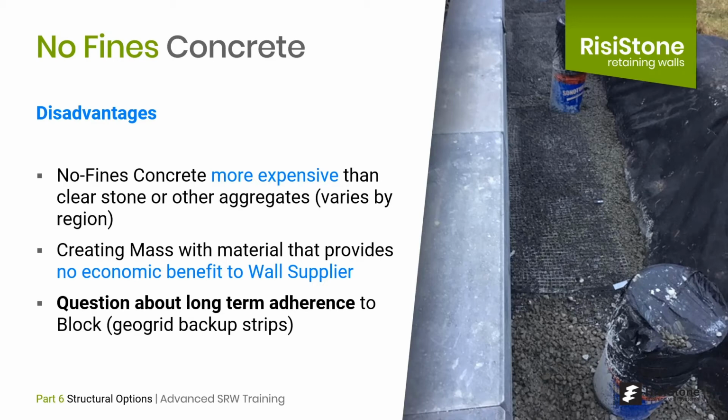From a wall supplier point of view, no-fines concrete does not provide any additional benefit, as most of the wall mass is created by a product that you are not supplying. But this is really no different than a geogrid reinforced wall. Finally, as mentioned, I do have some concern about the long-term adherence of the back of the block to the backfill material, the no-fines concrete, which we deal with by adding small layers of reinforcement as shown.